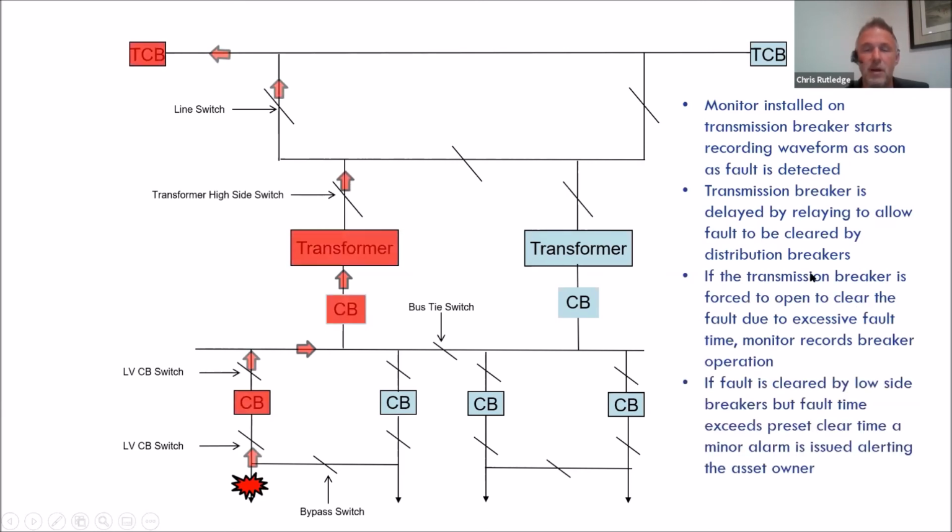Click through these. So what we end up with is years and years of continued excessive exposure to through faults on this particular transformer, at which point we have those mechanical and thermal effects on the transformer that we spoke about earlier. And with duration, it's interesting because duration tends to lend more to the thermal impact on that transformer. So we'll see a breakdown of the solid insulation the longer these through faults are held, and eventually the cumulative effects of this will add up on this transformer to the point that the next little through fault that's nothing will actually fail a transformer.